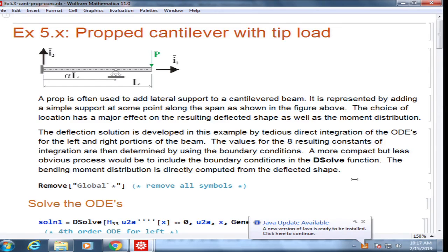We write boundary conditions or reaction forces when we are drawing shear force diagrams or bending moment diagrams, because our goal is to identify those, and a given loading could be in a particular region. For example, if I have a beam like this with a simple support, and my load is only applied here, when I'm writing the bending moment diagram, I take a section here and I consider everything on the left. Then this load doesn't show up in this area, right? But still there is a moment there. How do I evaluate it? I calculate the reaction forces here and then find out what the moment is. But we are not doing that here.